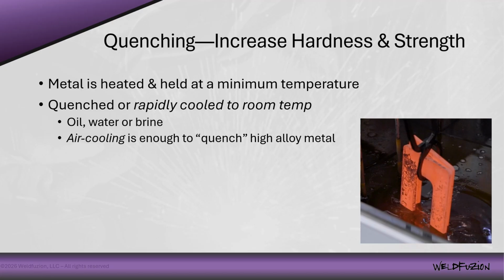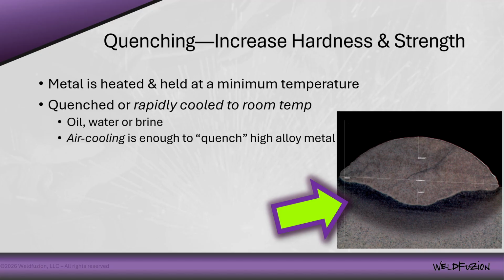So we often use different mediums when we're trying to achieve different levels of hardness, right? You might use oil, salt water, or a brine, or you could use pure water. Different quench mediums have different quenching rates. If a material is quench hardenable, this is going to form a non-equilibrium phase. In high alloy steels, it's going to be called bainite or martensite, which can form, and they're hard and very durable and wearable, but they can be brittle and be more crack sensitive.